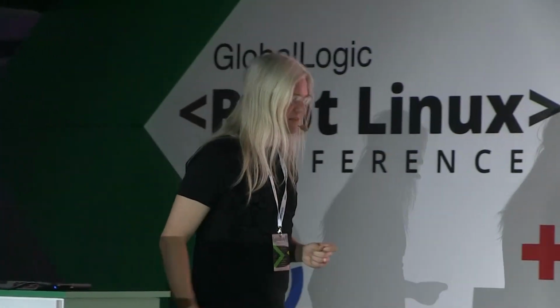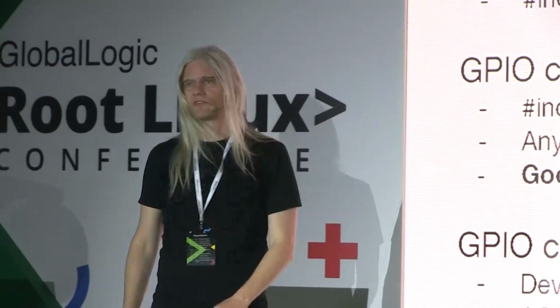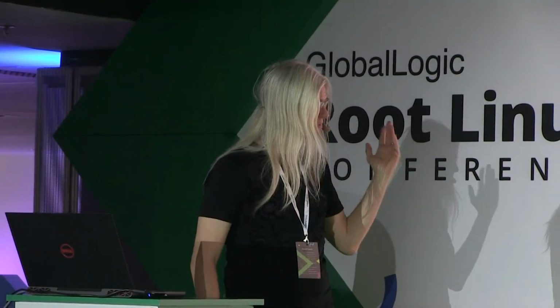Please help. So what we are using now are descriptors, and they are opaque cookies. It's just a pointer, and you get it from this consumer interface here when you use it as a user. The drivers get an offset from 0 to n on their controller, and we create the GPIO handle from there. If you need interrupts, you can convert these descriptors into an interrupt line number, which is nice.